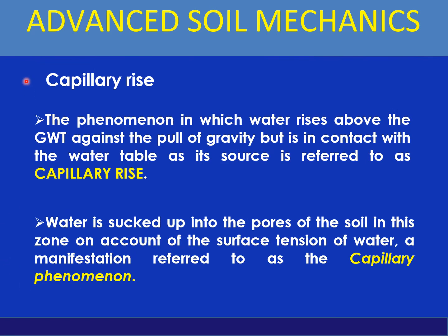Capillary rise. The phenomenon in which water rises above the groundwater table against the pull of gravity but is in contact with the water table as its source is referred to as capillary rise. Water is sucked up into the pores of the soil in this zone on account of the surface tension of water, a manifestation referred to as the capillary phenomenon.